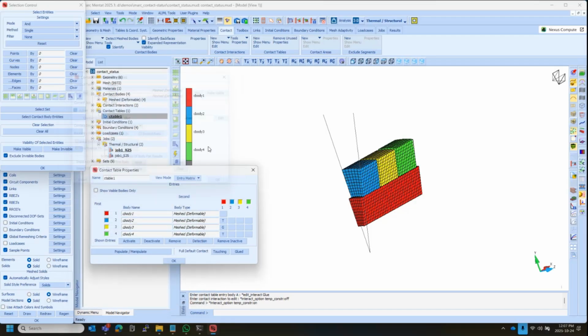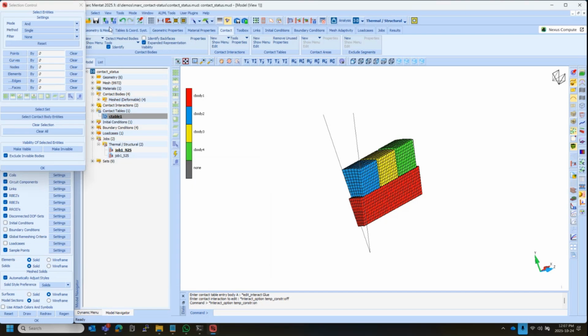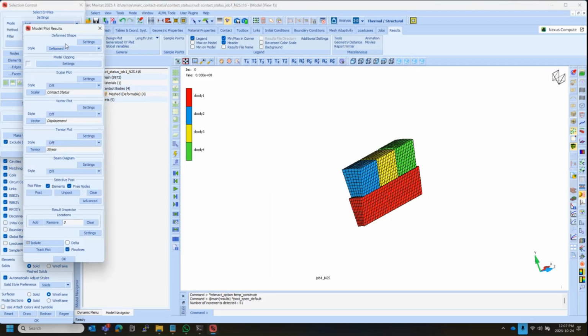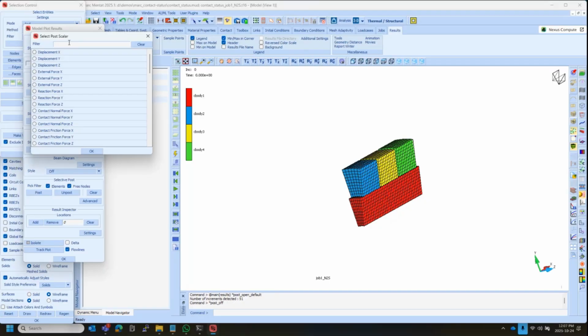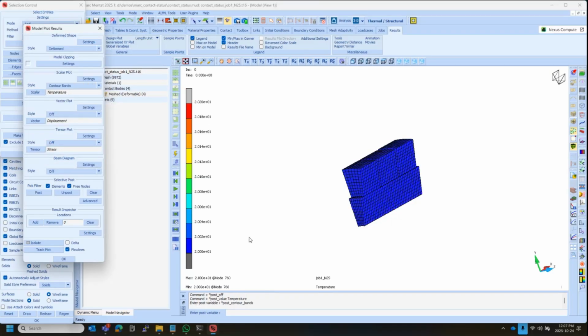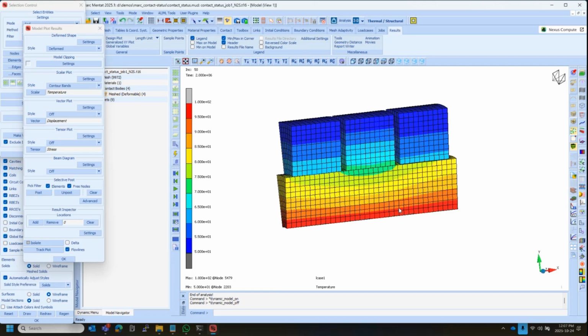So if you activate that, which is the default, at least in the latest version, it's perfect heat transfer at that location. Okay, so if I now go back to the model again of the results and plot in this case the temperature first, and activate temperature. So everything starts at 20. I apply a high temperature, I think 100 there and 50 on the outside. So you can see how the temperature is transferred between the different regions.